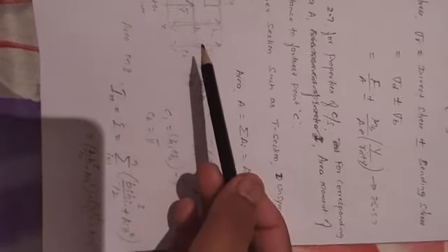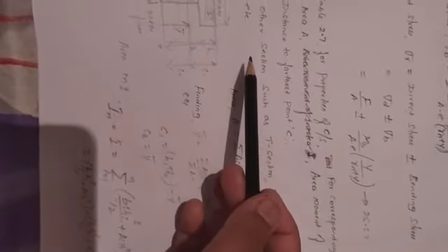How do you find Y bar? As you know, in elements of civil engineering, this formula is used for different cross sections: the sum of A_i into y_i divided by the summation of A_i, where i is from 1 to n portions. From this, what is C1? C1 is from the central axis to the inner fiber: H1 plus H2 minus Y bar. Outer fiber C2 is Y bar. Suppose if you want to calculate area moment of inertia, a general formula is used. I think you already heard about this in elements of civil engineering and also in mechanics of materials, right?